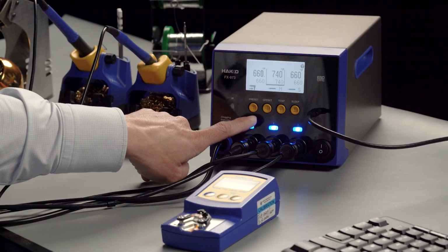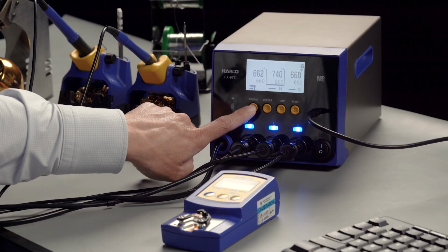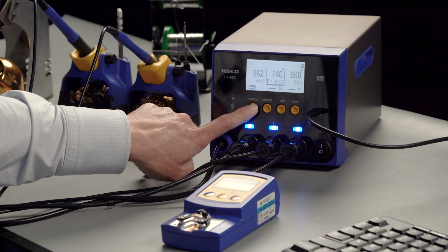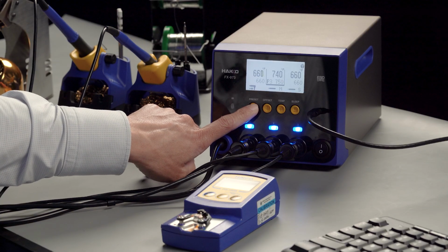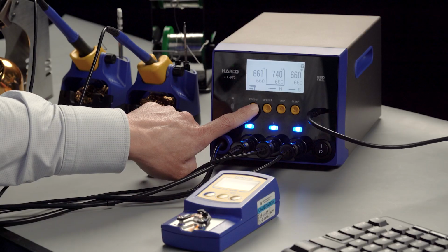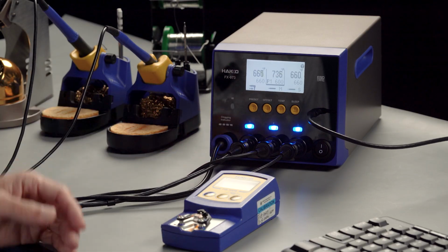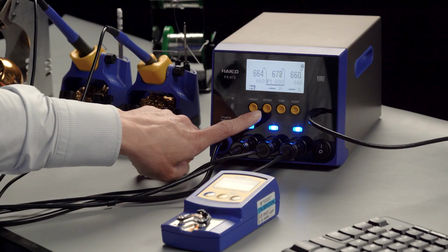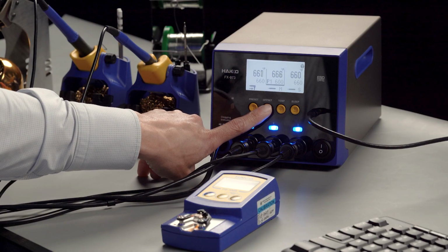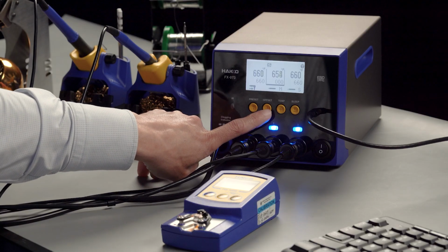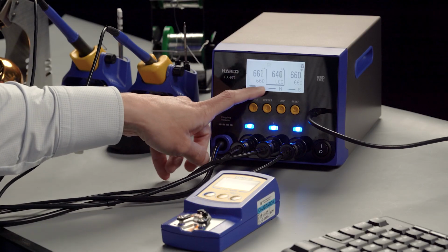But in this partial lockout mode that I just created, I do have access to offsets and preset selection. So let's make sure that on channel 2, I press the preset, and there you go. I do have access to make changes or select different presets. So I hit enter, and I can make adjustments to the preset selection that way. I also should have access to my offset, so let's make sure of that. I press the offset button, and there you go. I can still enter an offset value.